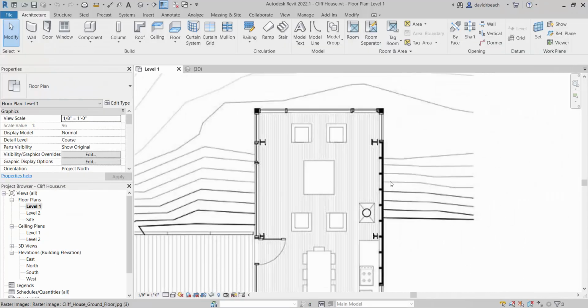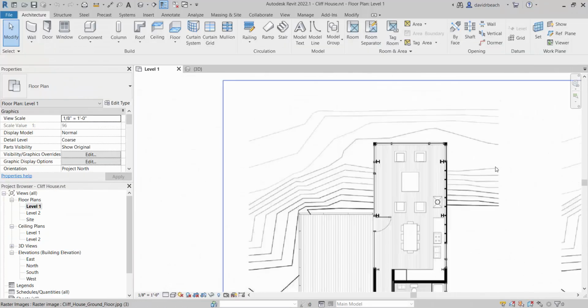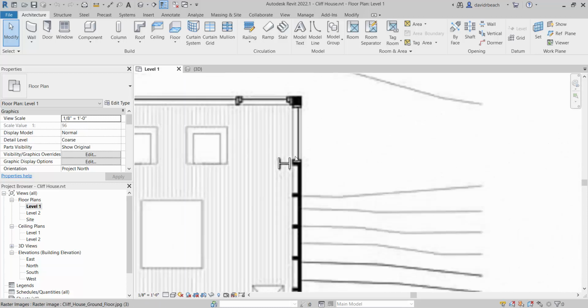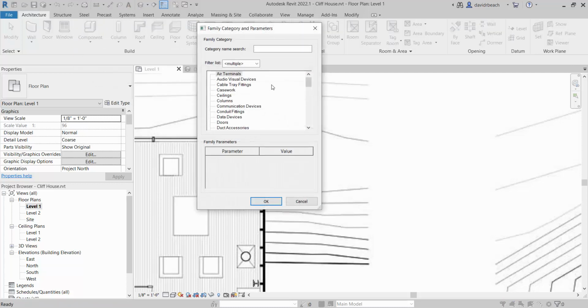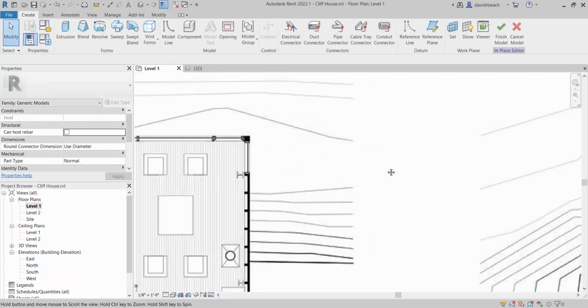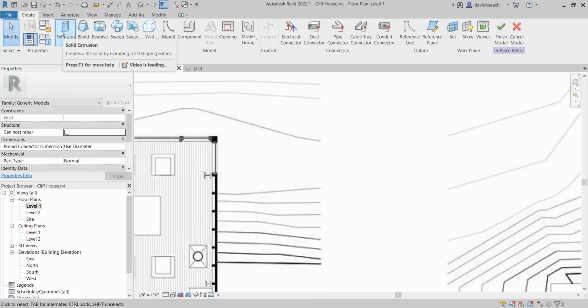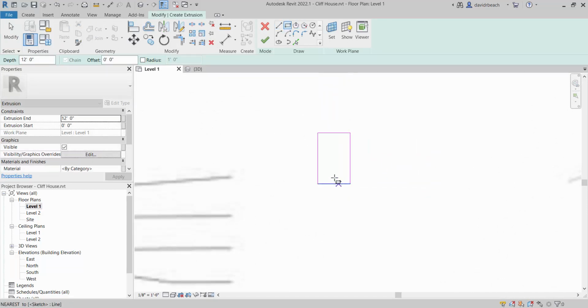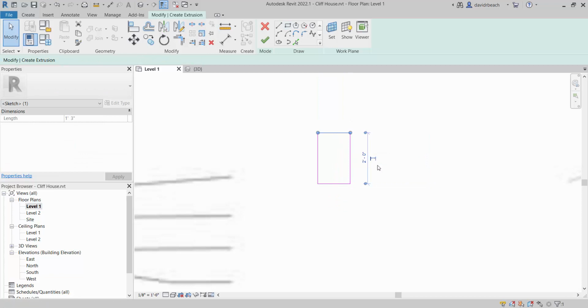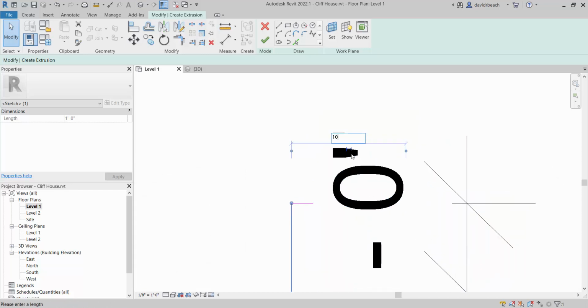This is one of those sessions you might want to go back and watch again, on Revit custom components. So again, to model those columns, what I had done was Component, Model In Place. Again, when you're learning this content, we're using generic models. We're using the extrusion. An extrusion, the easiest way to model something like a column, is just to start with a box. And I believe it was 1 by 10.